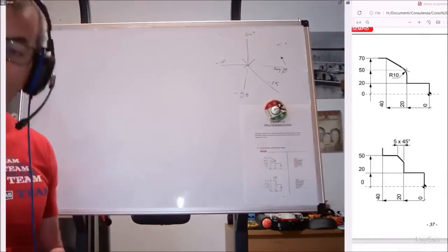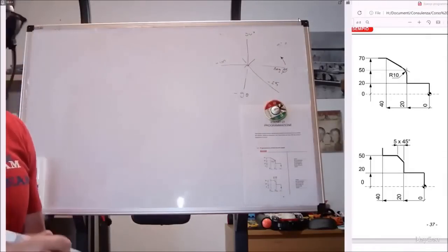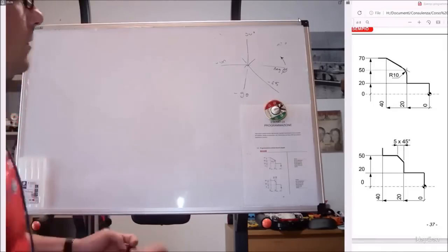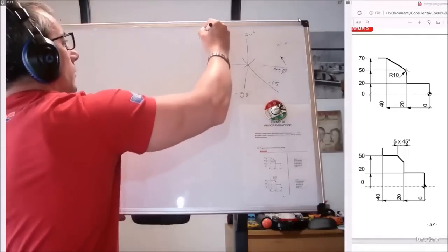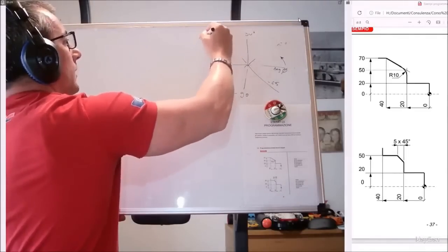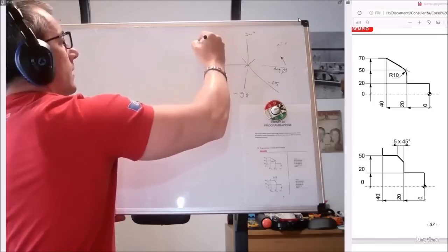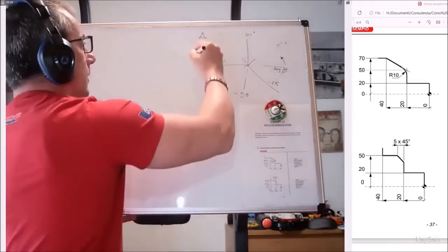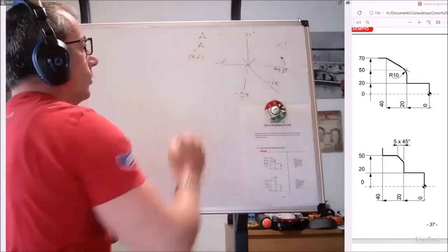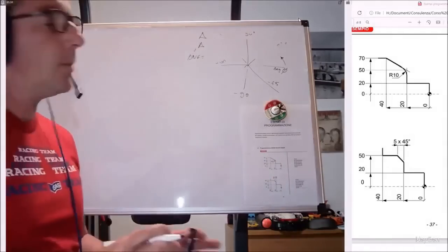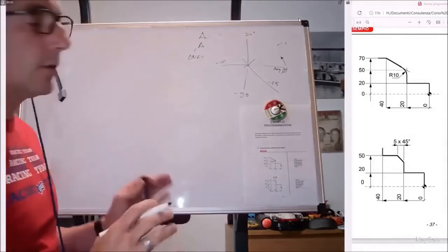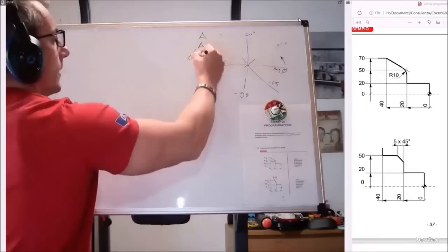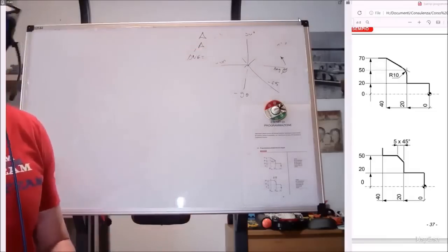As for programming purposes, it is normally done with an A representing angle, in more recent Fanuc models, while within Siemens, you use ANG, ensuring that you understand this concept clearly. The concept is what needs to be learned, not the letter that is placed in front of it.